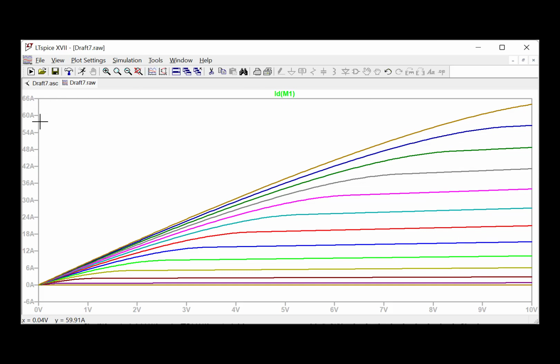As I have shown you earlier, in DC conditions, it would be safe to use these transistors only up to 20 amps of current, which is the absolute maximum rating for the DC current of a transistor like this. In pulsed condition, the transistor can reach much higher current levels. And basically, this is what we can somehow imagine to simulate by means of a simulation like this. Keep in mind that, of course, if you're planning to use a transistor like this in DC condition, you would need to avoid going above 20 amps. This is the first thing I wanted to show.